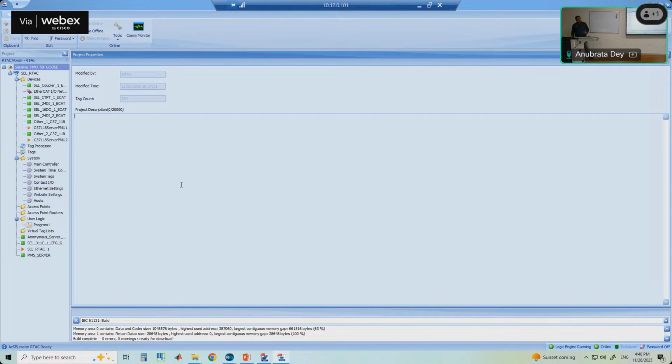This Axion device is not doing anything. It is just the digital output signals. It is redirecting, giving it back to the RTDS. So it is just a hop. Here we can design our own logic, because in a utility we cannot change the settings of the relay. So if we want to test any of our own logic, we can use this other device. It also has inbuilt RTX. We can design some logic here, and based on that we can send the GOOSE. From here the output is digital out, and in the RTDS it is digital in.